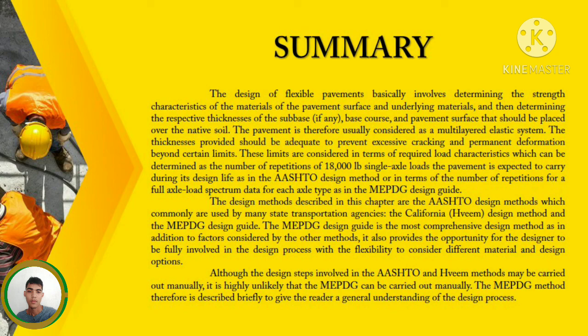For the summary, the design of flexible pavement basically involves determining the strength characteristic of the materials of the pavement surface and underlying materials, and then determining the respective thicknesses of the sub-base, if any, base course, and pavement surface that should be placed over the native soil. The pavement is therefore usually considered as a multi-layer elastic system. The thicknesses provided should be adequate to prevent excessive cracking and permanent deformation beyond certain limits.